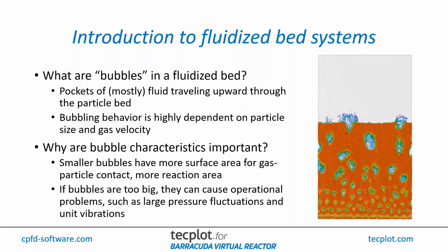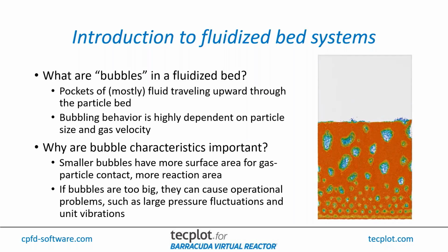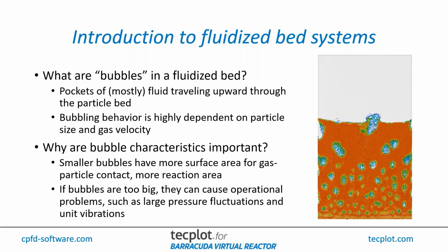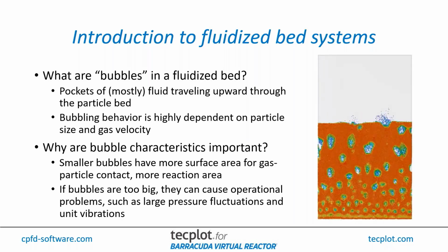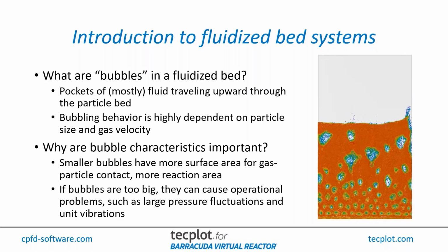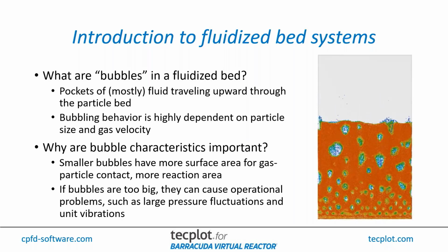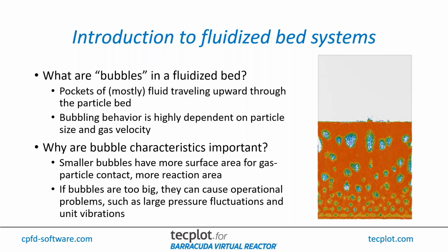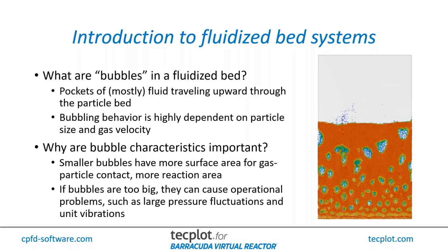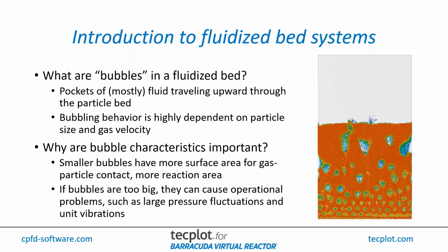Since today's webinar is about analyzing bubble characteristics, I want to make sure it's clear what we mean by the word bubbles in fluidized beds. The animation shown here is a thin gas solid fluidized bed, and this is the example system that we'll be using for the live demo portion of the webinar a little bit later. The particles have been colored by volume fraction, which is how densely packed they are relative to each other. Red regions have particles that are densely packed together, while the green or the blue regions have more dilute particle loading. We call the regions of relatively low particle loading bubbles.